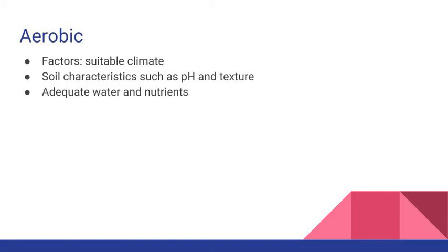It may be difficult to treat them using technologies that rely on volatility, such as SVE. In addition, biological remediation treatment often does not require heating, which is good for conserving power. It usually requires relatively inexpensive inputs, such as nutrients, and usually does not generate residuals requiring treatment or disposal.